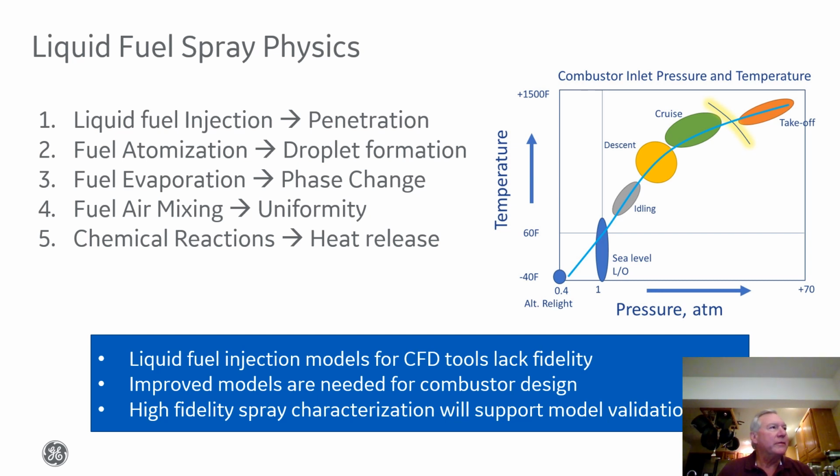So along with all the testing that we do, we also are trying to mature CFD methods to help our design process. In particular, in our CFD models, the liquid fuel injection models are woefully inadequate to represent this large range of conditions that we experience in the combustor.